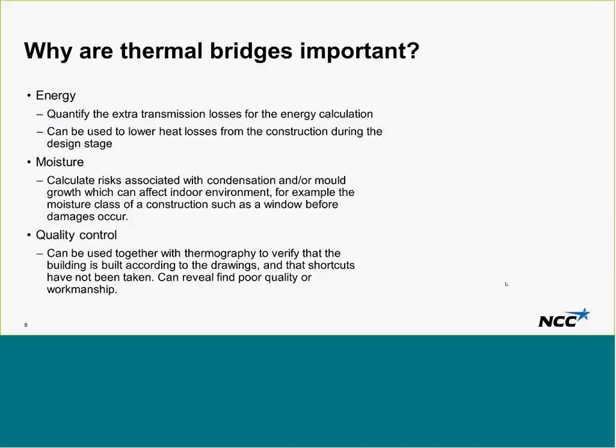So a quick question: why are thermal bridges so important? Well, from an energy perspective, it affects the energy calculations. In low energy houses, it becomes even more important to take into account thermal bridges because they represent a larger percent of the total heat loss.